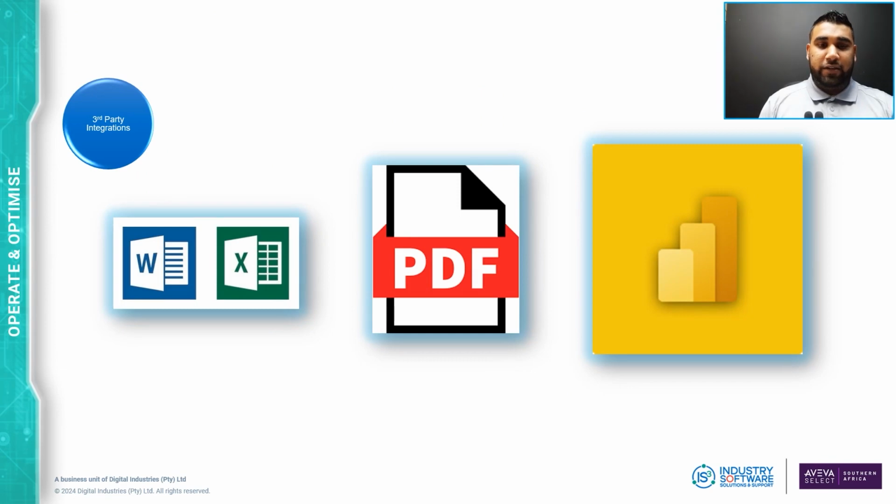Next, we're looking at third-party integration or external content. External content refers to media content outside of a Galaxy that can be linked to a view app and displayed during runtime. System Platform includes some pre-built apps to show content specified by external content items, such as web content, Microsoft Word documents, images, and more. To associate external content to a view app, you can manually assign the external content item to a layout pane. You can also link an external content item to an automation object for autofill navigation. A single external content item can be linked to multiple objects. The Power BI OMI app provides a set of interfaces to interact with Power BI report pages.